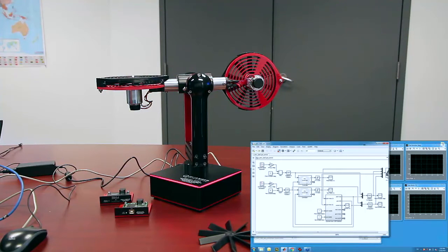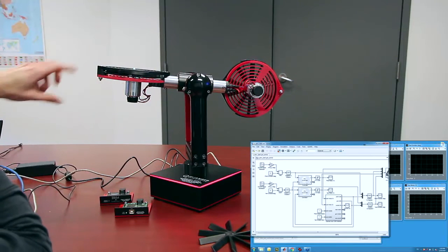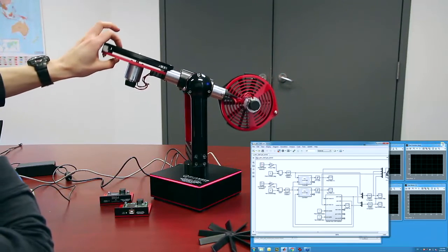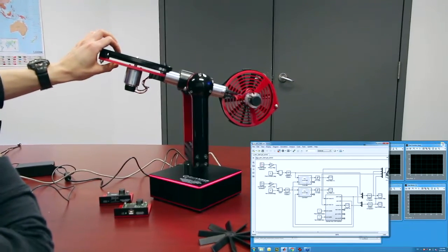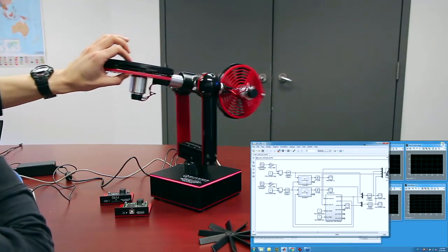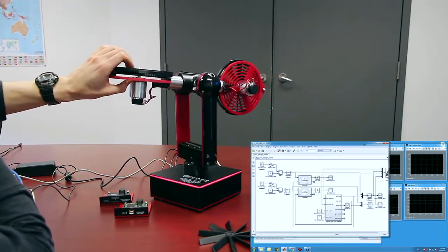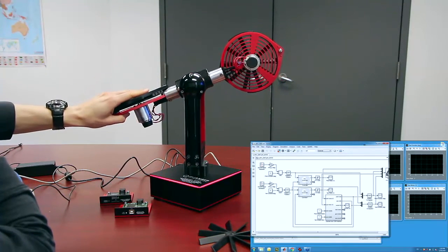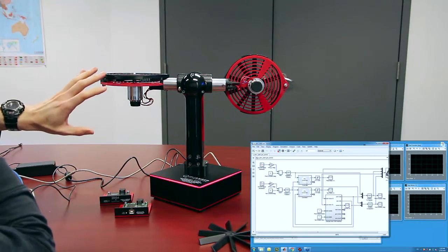Now the thing is, with this configuration, with the 2DOF helicopter, there is a huge coupling effect, right? You get these coupled dynamics between the pitch axis and the yaw axis. For example, when I apply a voltage or torque to the pitch, that will also affect the yaw. It will actually create a torque along the yaw. Similarly, when I'm changing the rotor speed, the torque of the yaw, it will exert a torque on the pitch axis, right? These two are constantly affecting each other.